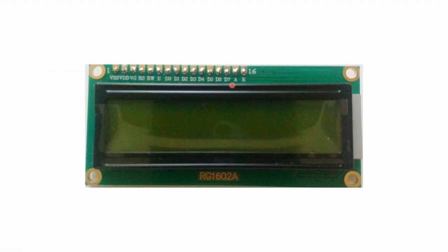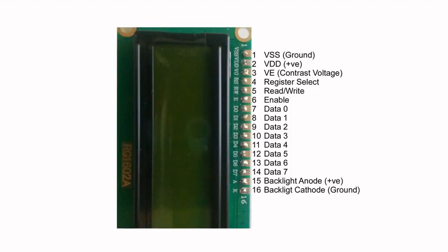All right, so in this video, we are taking a closer look at the LCD module and how to program it to display information. So let's take a look at what they call the pinout of the LCD module, and let me just zoom in and rotate it. All right, so the first pin, or pin 1, is VSS, that's ground. Pin 2 would be VDD, that would be the positive voltage, and then pin 3 is VE,